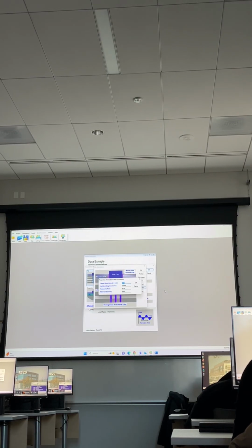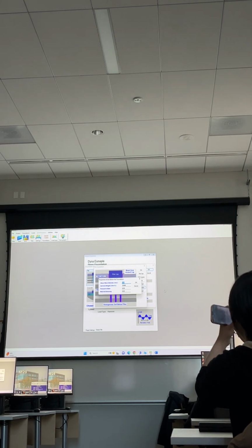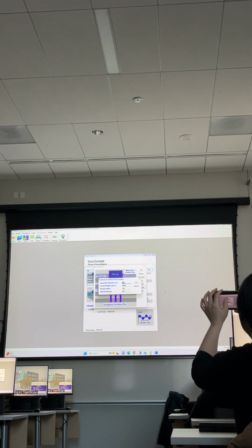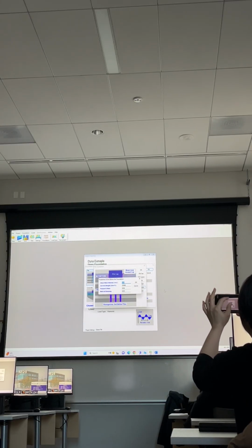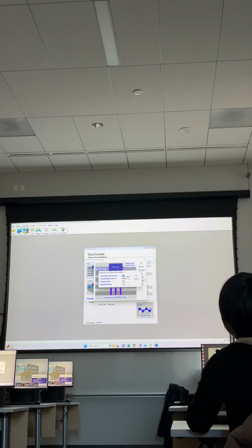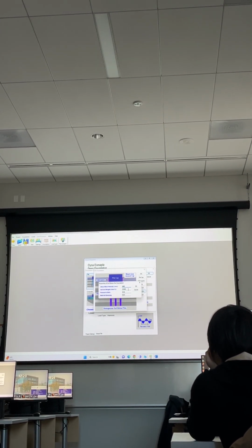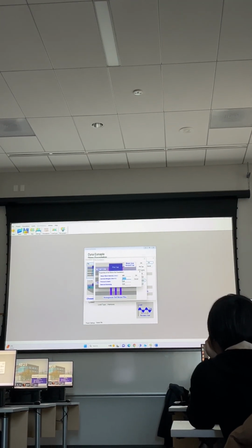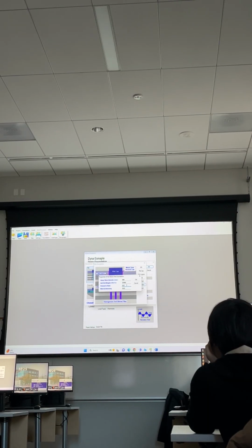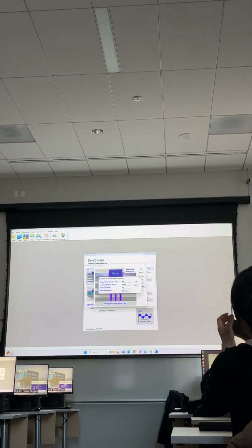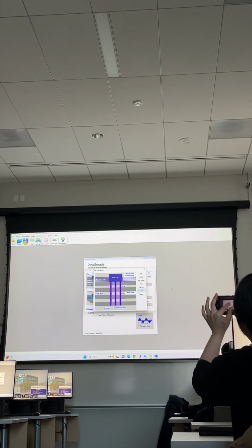After we define the applied soil, we can now define the soil below. This is the soil below the pile depth. So let's assume it is good soil, with shear velocity around 400. The Young's modulus is okay, 21,000, Poisson's ratio 0.3. And the damping ratio, we'll assume it 0.2.